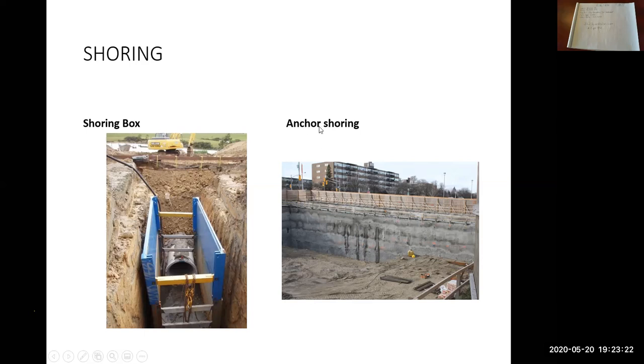And then where the anchoring part comes from is, on a required spacing, anchors are drilled into the wall to help support the shotcrete. So we'll do an example of that later today on how to calculate those quantities. So shotcrete, anchors, grouting, all that type of system.